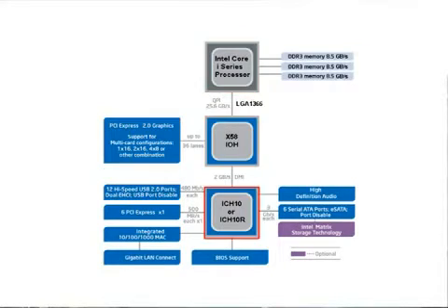Now the south bridge component in motherboards has been pretty steady in its functions for many years now. We have connections to things like audio. We have all of our hard disk, our serial ATA or parallel ATA connections in some cases. We have USB. This particular chipset supports 12 USB ports. We have PCI Express bus slots. These are the slots other than video that you would plug cards into. We have things like Ethernet controllers, the motherboard ROM.